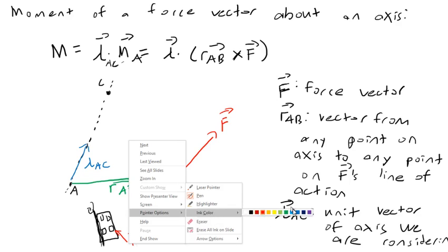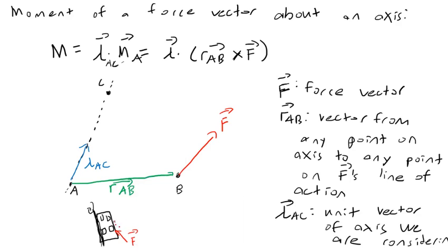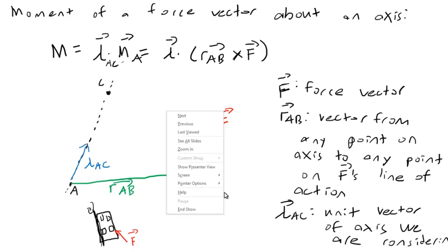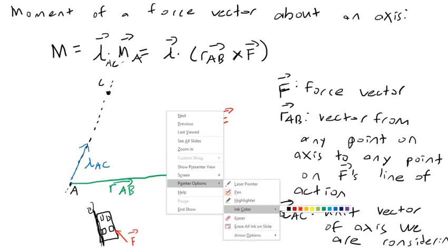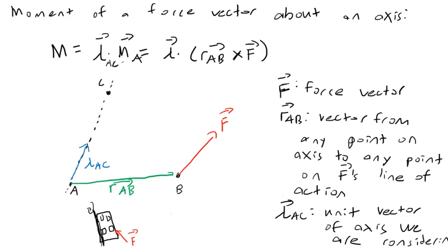See, in that case, if I wanted to calculate how fast the door will rotate, I wouldn't want to use the entire moment this thing generates about a given point. I would want to calculate only the moment that is in line with this axis, because only that is actually going to cause the door to rotate. The rest goes into applying forces maybe toward the hinge or something like that, but it's not going to actually accelerate the door in any manner.